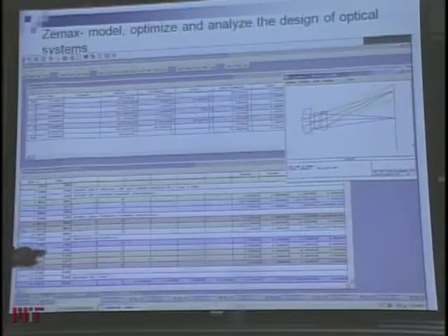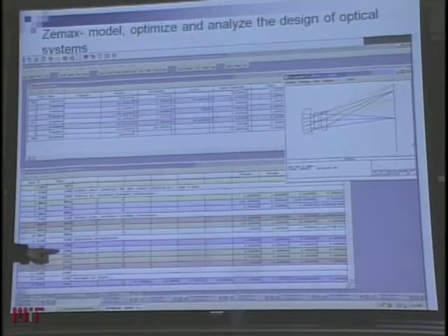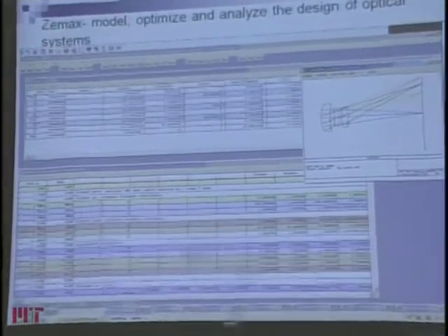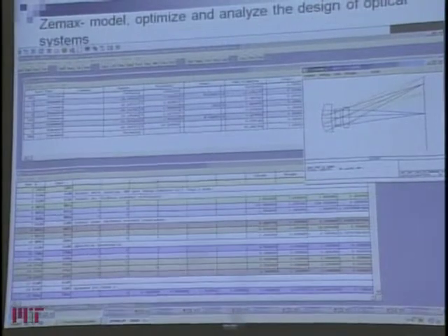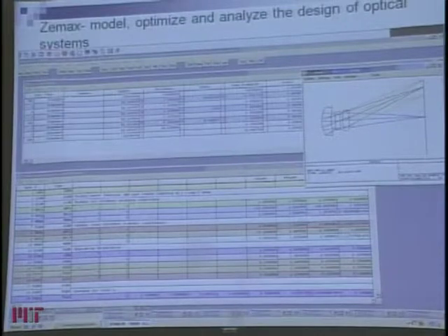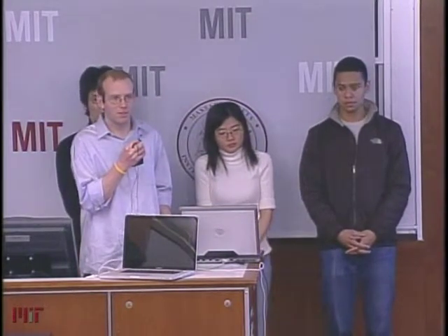This image shows basically the Zemax user interface. Here's where we define the merit function, which solves for the coma and primary aberrations, then sets constraints on the lens parameters. And here's where we defined the initial values and also what we wanted to use as a variable in each simulation. This one's set to vary all the curvatures, all the distances, and the glass types, which results in, theoretically, if you want to test 10 things for each one, 10 to the 14th variations. But Zemax is good at sifting through that to reduce the number of tests you have to do to find the optimum. In this case, it ran about 10 to the 10.